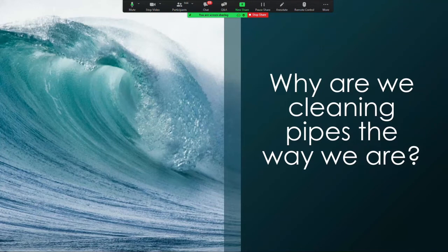Yeah. It's all related to what the mandate is from your utility or from your environmental association, whether it's EPA or Environment Canada. It all depends on the scenario as well. If you're in an area that has excessive grease or is problematic with areas like that, you may visit more frequently. If you're just doing your run through town and doing your circuit, most municipalities I deal with are either on a 4 or 5 year program to get through town, but there are areas that are problematic. Think of places where grease congregates, where all the restaurants are, your fried chicken joints and your other restaurants, your burger places and stuff. They tend to have more grease issues and need more frequent cleaning.